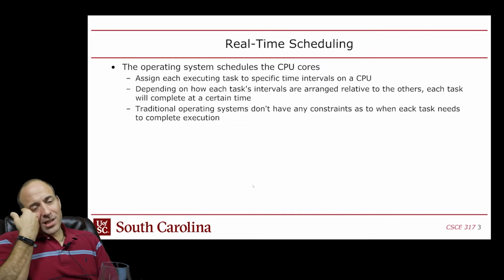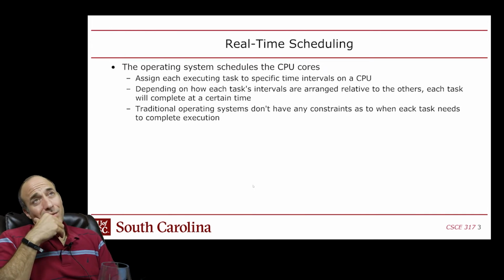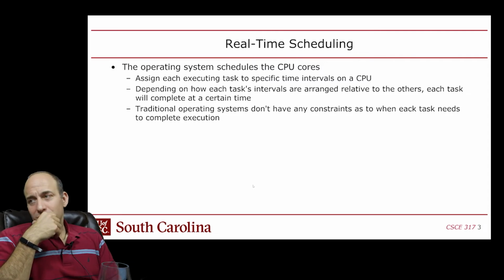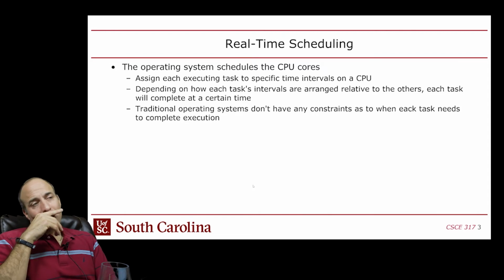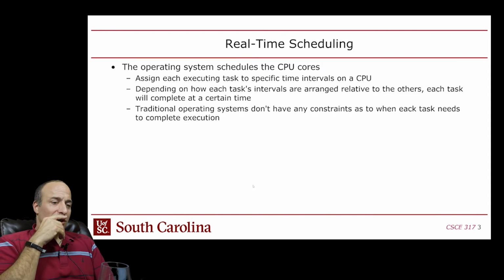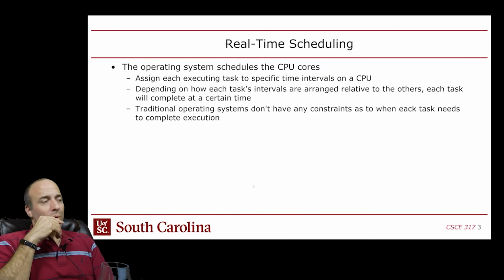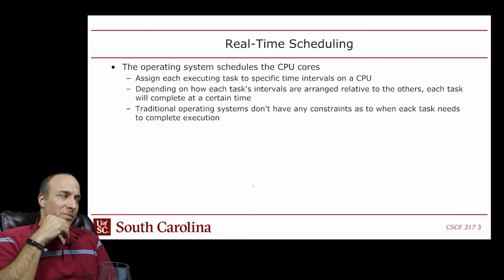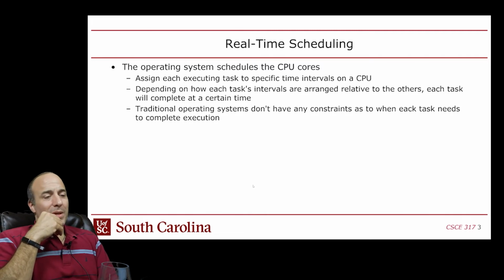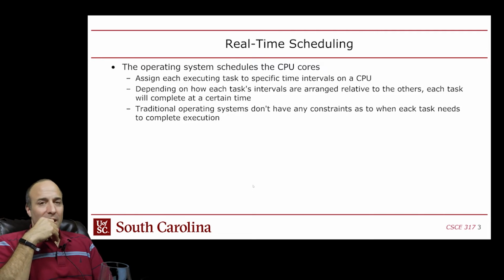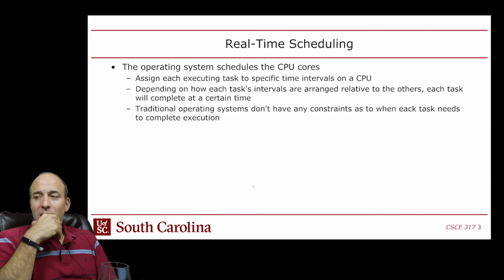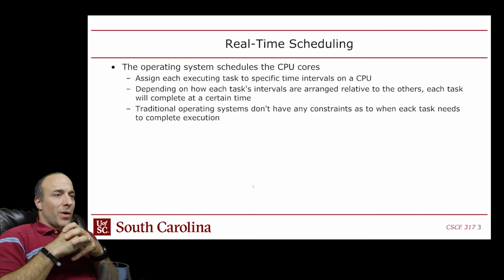I mentioned that CPUs have a lot of uncertainty in terms of their worst case execution time because of a whole bunch of reasons. CPUs are not designed to be predictable. That's because their memory systems are complex and unpredictable, as well as their interrupt systems, virtual memory systems, and so on.